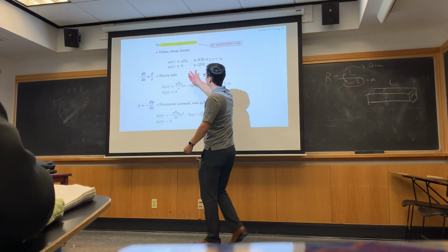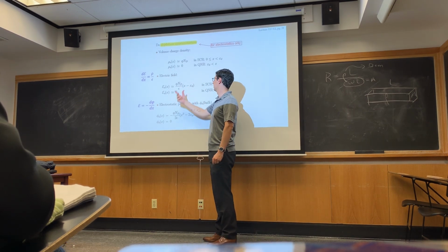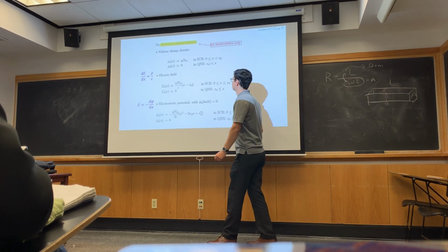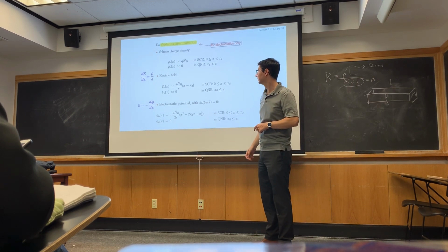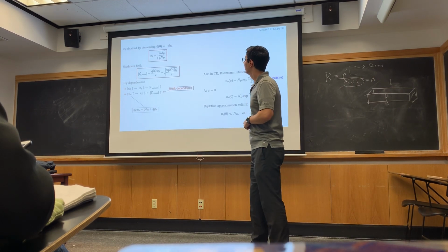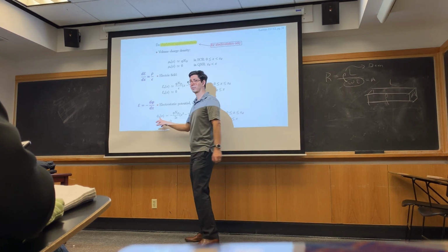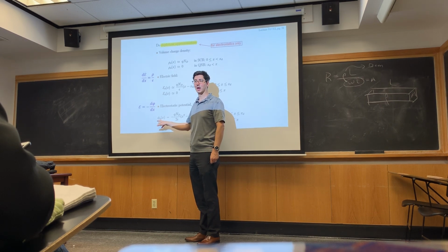Okay, so I'm taking that rectangle, integrating it, getting a linear function, integrating my linear function, getting a quadratic function. And all these are starting from xd, so that's why I have xd's in my solution. I know the potential from xd to 0 has to be phi bi.